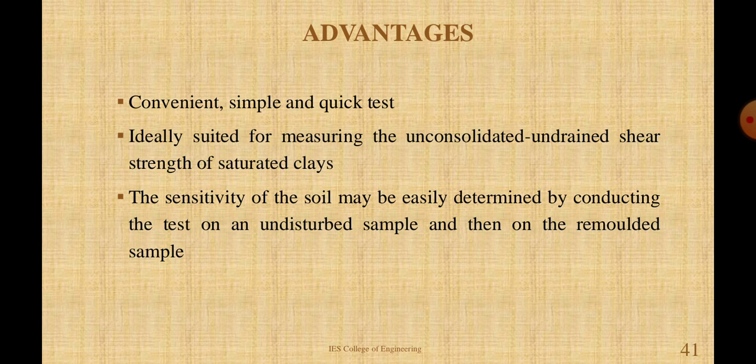Then the advantages of unconfined compression test. It is a convenient, simple and quick test. Ideally suited for measuring the unconsolidated undrained shear strength of saturated clay, and the sensitivity of the soil may be easily determined by conducting the test on an undisturbed sample and then on the remolded sample.